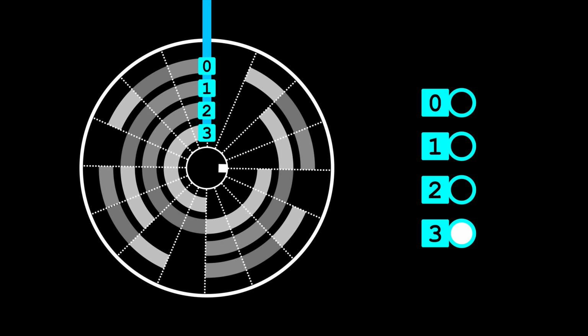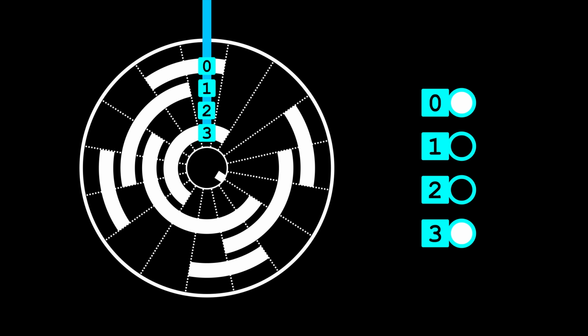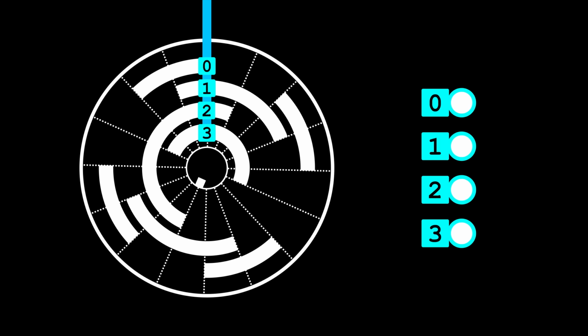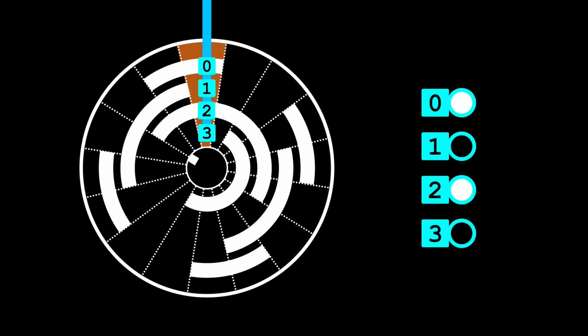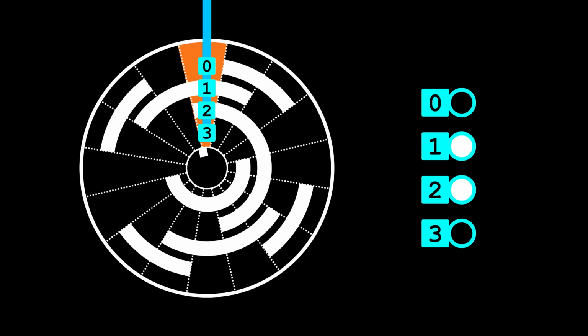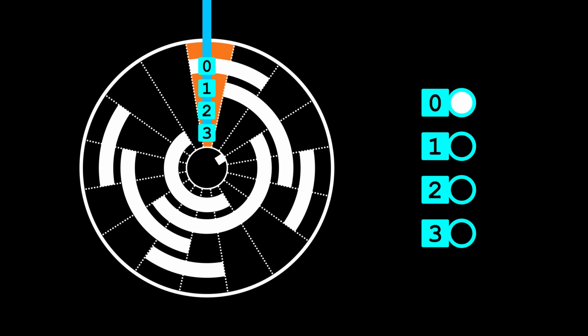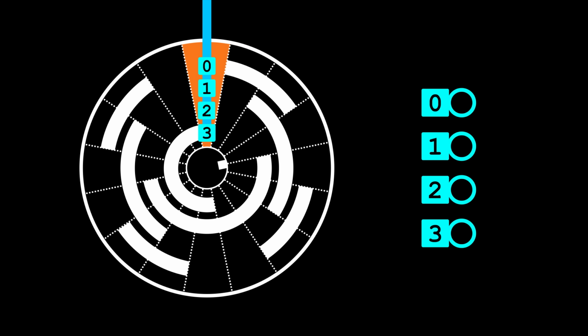Same setup, but the encoder wheel layout has changed. Now, only a single track ever starts or ends at a single location. This solves the problem seen before, and means that the maximum uncertainty is only ever between 2 neighboring sectors. Which, fair enough, I think that's actually a totally legitimate response when transitioning from one sector to the next. If you want more precision, you'll just have to add more sensors and more tracks.